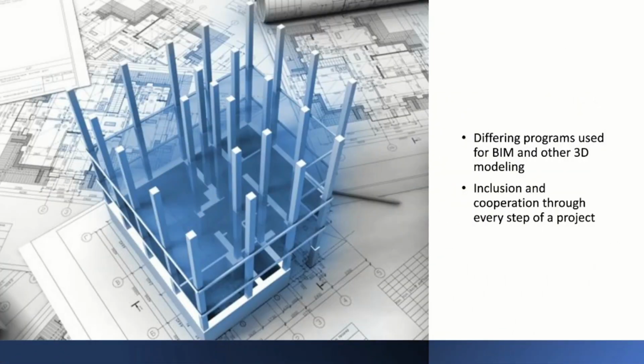BIM applications, such as Autodesk's Revit, allow different views of a building model for drawing production and other uses. These different views are automatically consistent, being based on a single definition of each object instance. BIM modeling software also defines its parameters and relations to other objects, so that if a related object is changed, ones around it will automatically also change with it.